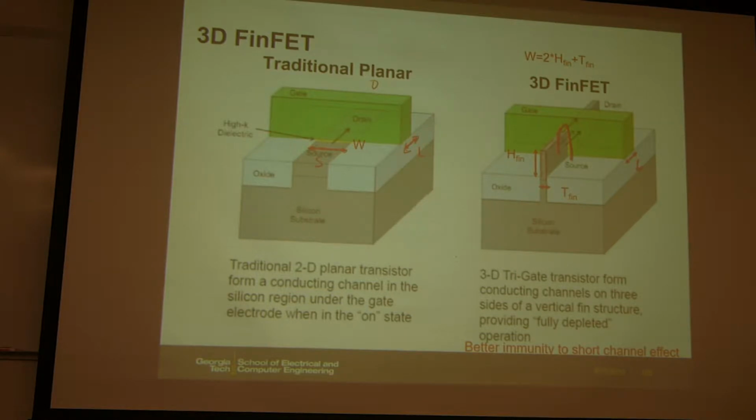And then the top, in many cases we have this tri-gate, a 3-side gate. So then the top is also in contact. Then the thickness of the fin is also in this W. So now the W becomes this. This is the W over L, that W. Or sometimes we call this the electrical W, because electrically the current will flow proportional to the W.